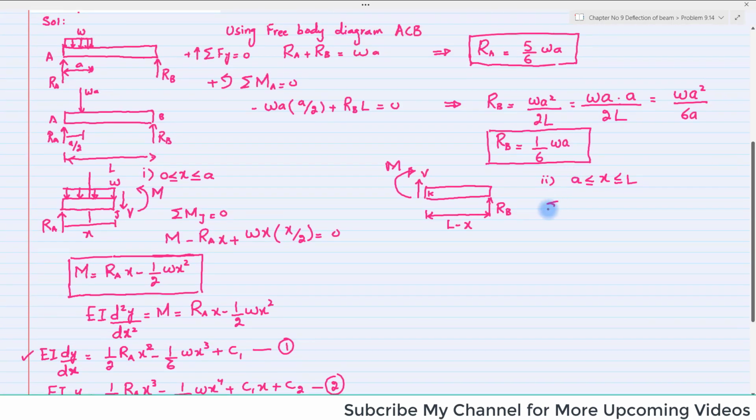Again, the sum of all moments about point K is equal to 0. You can see there is a moment which is clockwise, so it will be minus M, and due to this reaction force RB, the perpendicular distance is L minus x, and it will be counterclockwise, so it will be plus RB into L minus x. Their sum must be equal to 0.